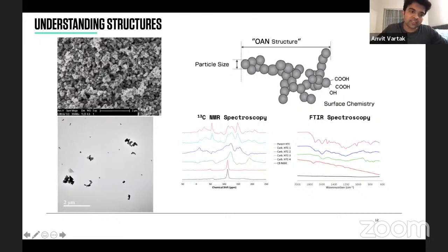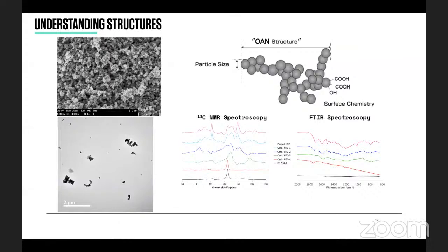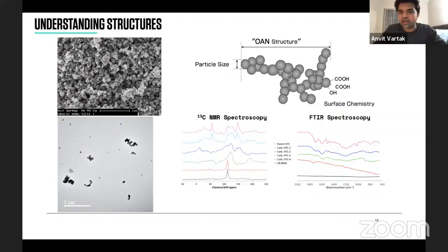And this is TEM, which is transmission electron microscopy. This doesn't show you surface characteristics, but it is helpful in knowing how many of these aggregates are formed in your material and how much you need to break it down to get to a smaller particle size, so your material can be better at reinforcing the rubber that you're using it as a filler into for the tires.